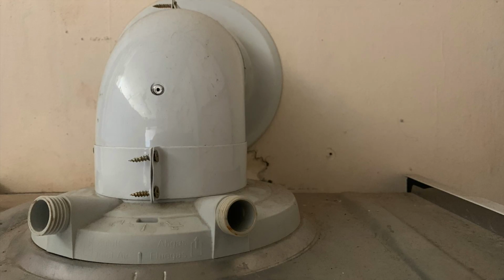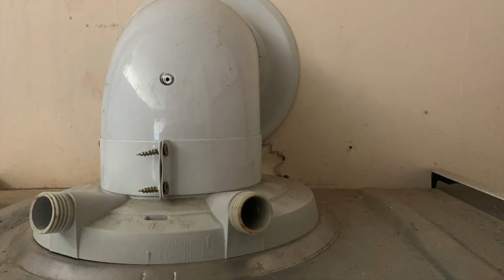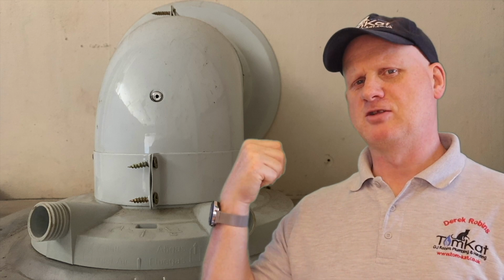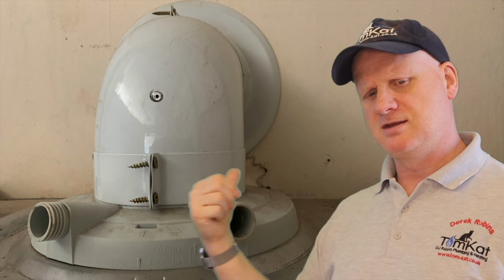Now this picture represents you going to service this Vaillant boiler and you find this when you're inspecting the flue system. What would you categorise this as? Did you actually notice quite a few faults on this? Or did you just concentrate on the major one? So let's go through it. First one is, did you notice the test caps missing? This has only just been added to this new version of IGEM 11, the second edition, and this is 7.2. Now in the old edition, the first edition, 7.2 was left blank. So this is now what it says in 7.2.